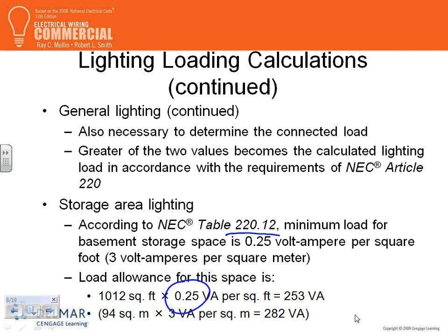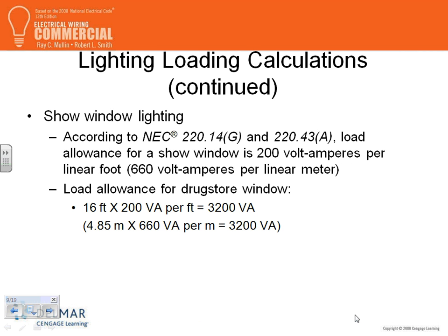Any question about that? But please read it, because you might have an area where half of the building is storage, like if you have a storage building with just one tiny office, and the other 90% of the building is just storage. In a case like this, it makes a whole lot of sense when you size the light for this area to multiply by 0.25. They're doing it by meter too, if anybody's interested in working in the metric system, which is not really a big deal.